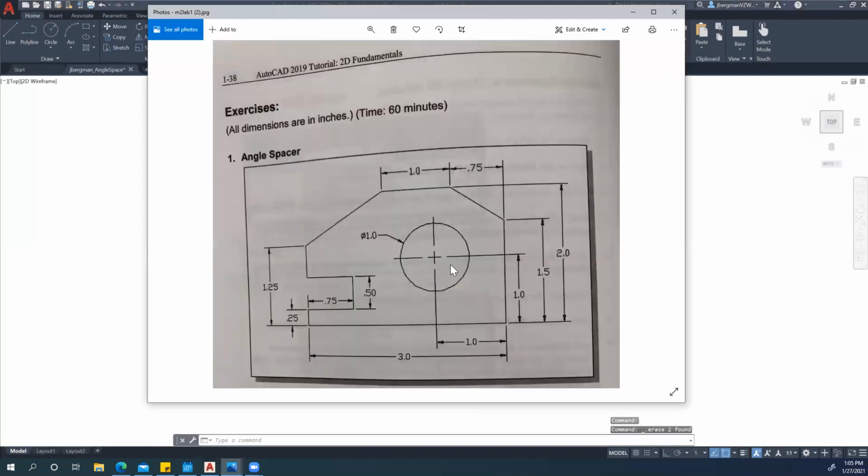And the last step is to add this circle. So the way we were just adding in the lines was a different way. There's different ways, according to the chapter, that you can actually add points. And so we were using the direct distance technique according to the book, but this time, or we're using polar coordinates, I'm sorry. Polar coordinates is where you type in a distance and an angle. So remember we were typing in 3 and then 0 degrees. So we're using the polar method. This time we are going to use the Cartesian or